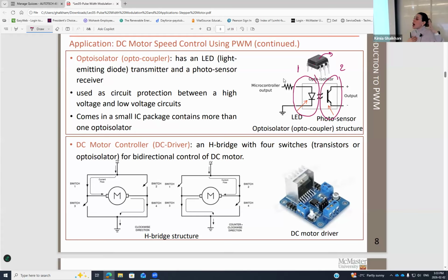Still, voltage is not something we can change. We can have that constant 5 volt, for example. But what we do is inside this unit or inside the program, we have to come up with some idea, some method in order to pulse that same 5 volt. Maximum still it is 5 volt. We wanted to pulse it, to go on and off, on and off, on and off, in order to be able to generate a continuous signal out of it.